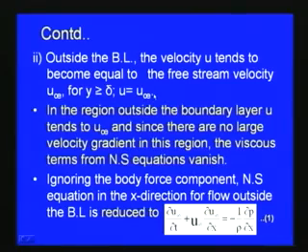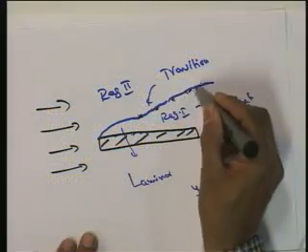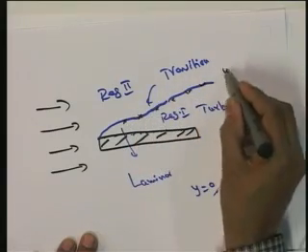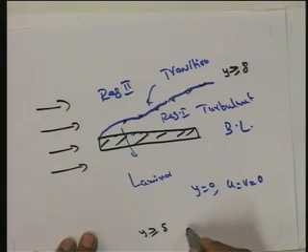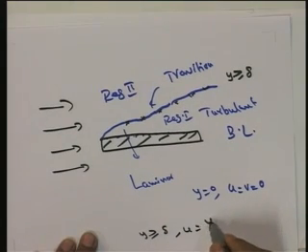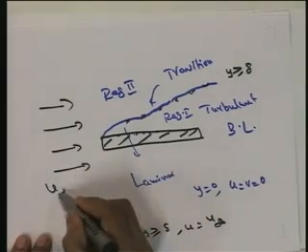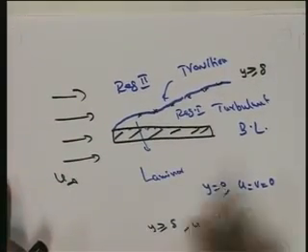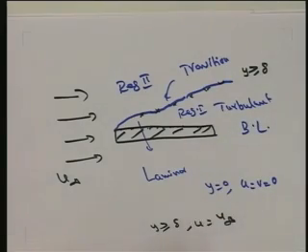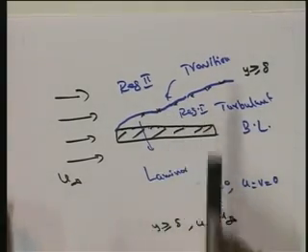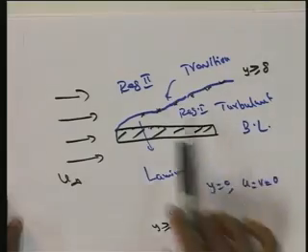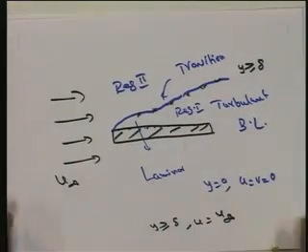Here, when we consider this boundary layer, Prandtl proposed that for y greater than or equal to delta, u is equal to u infinity, which is the free stream velocity. Like this he divided the flow into two regions, region 1 and region 2, and put forward the boundary conditions. In the region where the boundary layer formation takes place he used the Navier-Stokes equation, and beyond this potential flow theory can be applied.